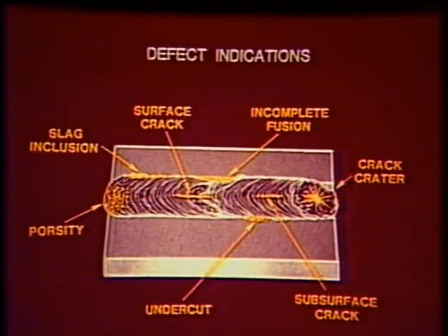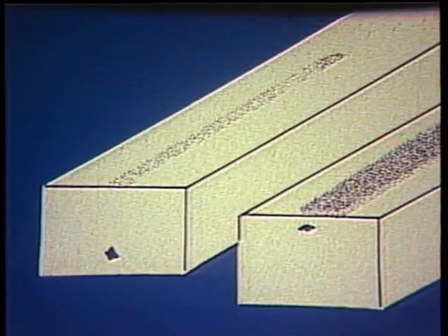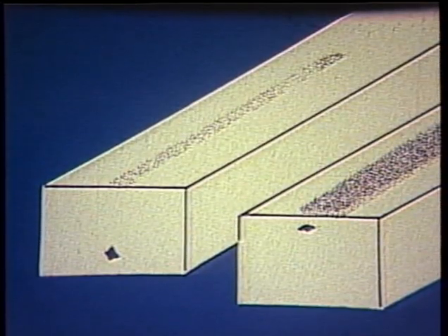When the proper procedures have been carried out, visual evaluation is performed on all indications displayed by accumulations of particles on the surface. The shape, sharpness, width, and height of the particle patterns are evaluated to determine the type of discontinuity or defect. The closer the indications are to the surface, the more defined the particle patterns will appear, whereas the deeper the flaw, the weaker or fuzzier the indication.